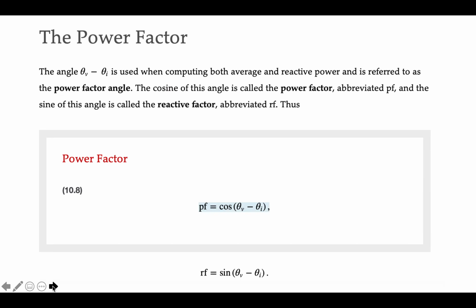So let's talk a little bit about the power factor. The power factor is important because it gives you a relative indication of how much of your power is average or real and how much of it is reactive. So for a given load or a given element or a given terminal pair, the power factor is the cosine of theta v minus theta I.